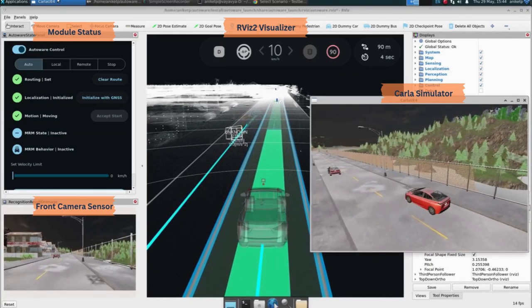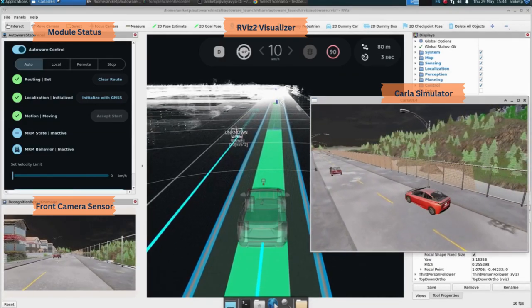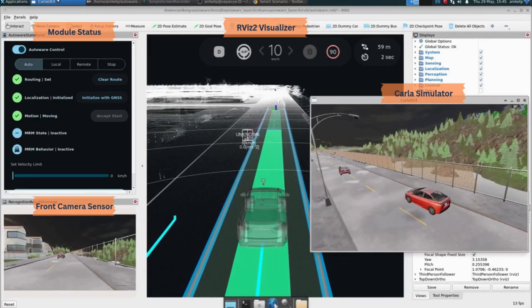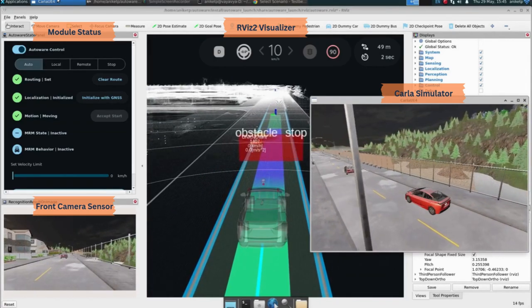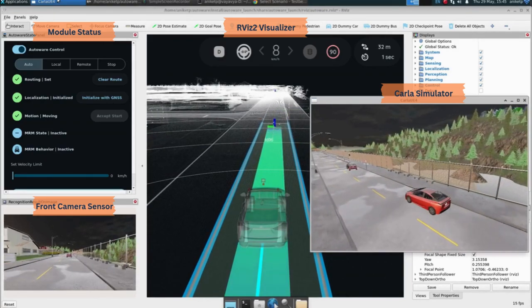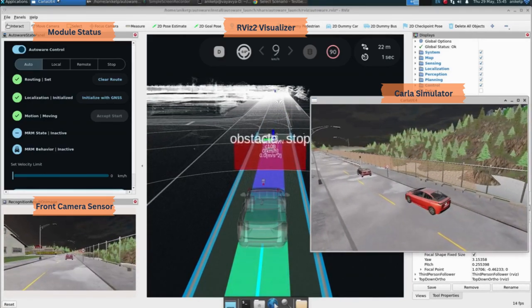The vehicle switches to autonomous mode and successfully handles a cut-in scenario where another car abruptly enters its lane and stops at a signal. As you can see, you can integrate sensor models, the Autoware stack, and the Carla simulator to create a complete L1 virtual ECU setup for scalable cloud simulation.